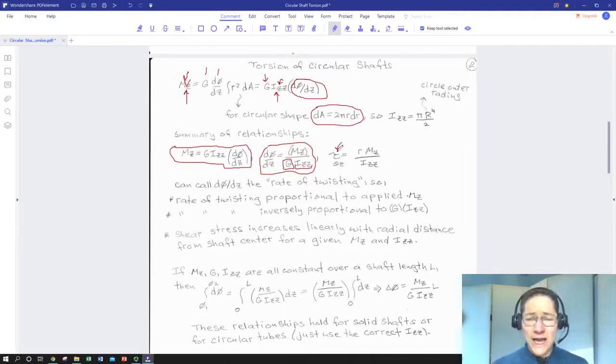So we might look at our yield strength of a material and then go through our Mohr circle stress transformations and say, okay, what is the max shear stress associated with my known tensile strength, my capabilities? And then that would be the max number that you would allow somebody to apply.